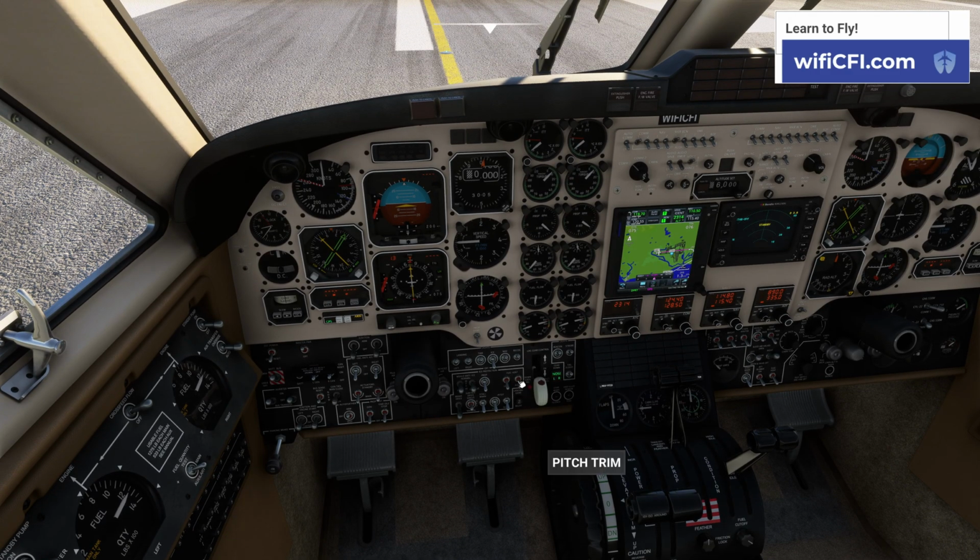Let's go ahead and get our hot items on. So there's 1, 2, 3, 4, 5, our heats, and our auto ignition, 6 and 7. So you can see we've got our ignition lights on. Exterior lights are good, transponder is good, flight director is good. So now we have everything that we need and we are ready for our departure.